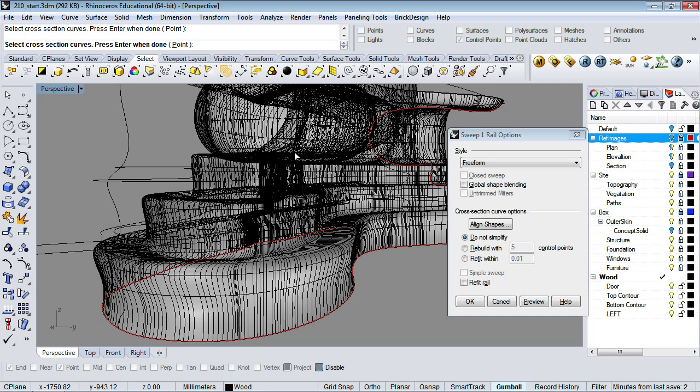You have to tell it in that process, like we just did. We would tell it, okay, use this, select the first rail, and then you select all of the cross-sectional curves as it goes around. And then it will look at all of those and morph between those. Okay. The important thing to remember is that those cross-sectional curves always have to touch the rail curves. They have to be touching. So use the intersect to get those curves together and make those cross-sectional pieces. Okay, and then it's a really powerful piece. Okay, so then let's cancel out of that.